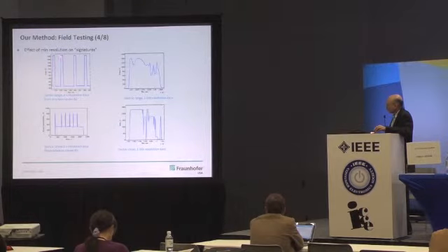For example, here we have approximately 15 seconds on, then about half a minute off. And this is approximately low setting. If you want to increase the temperature of the range, then the heating time will increase, but not the power. Now, what happens with this nice picture if you transition to 1 minute resolution in this very wild power consumption pattern? It is no longer on-off. That is, it can be considered as on-off, but with such huge oscillations that it will be very difficult to get meaningful information. The same thing is applicable to electric dryer.